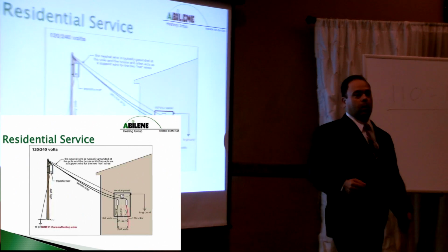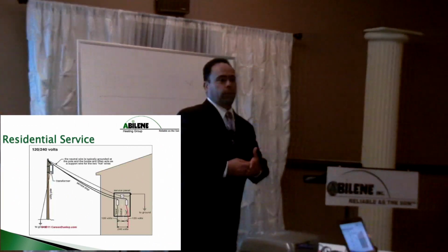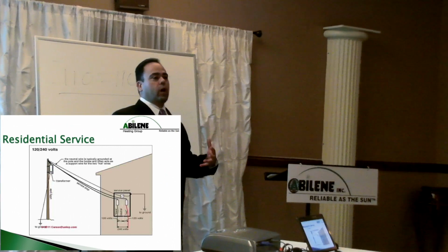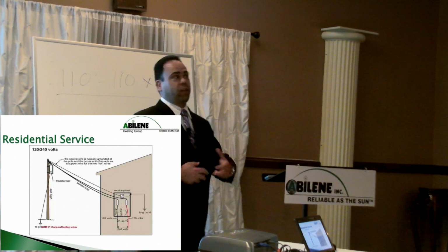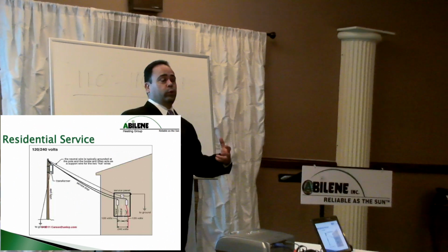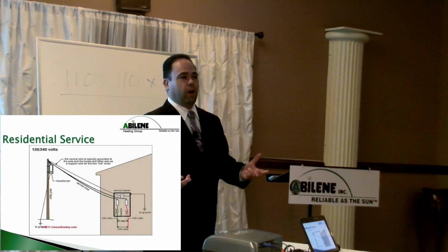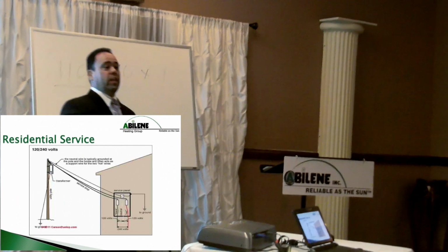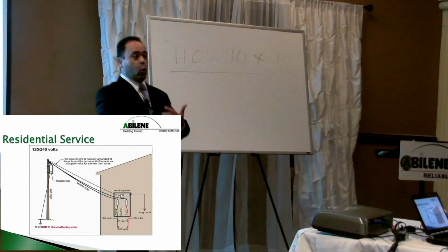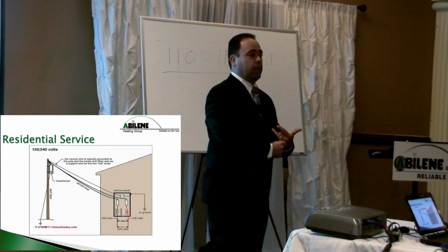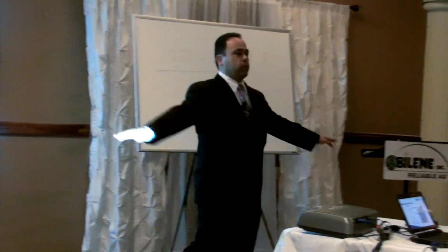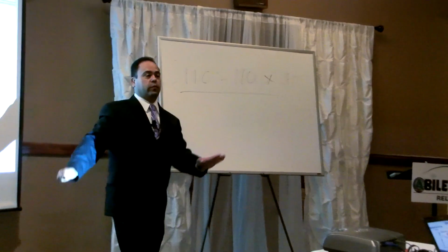start burning everything out. When you short something out in between neutral or into ground, right? It's an inrush of current. And that inrush of current, to protect everything else, remember, we said it's heat, right? Inrush of current is going to produce so much heat, that's what's going to start a fire. Okay? So that inrush of current, we want it to dissipate into the ground, which is your water main. In most cases, it's tied into a water main. A lot of times you'll see a ground rod driven into the ground. It has to go out into the ground. Okay? That's the main reason for ground.